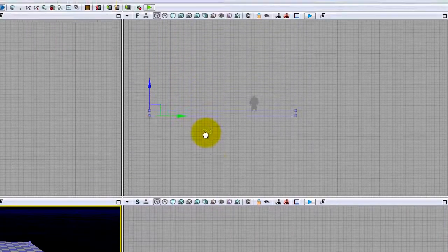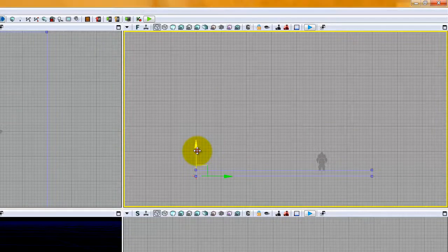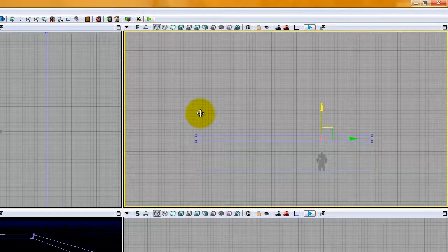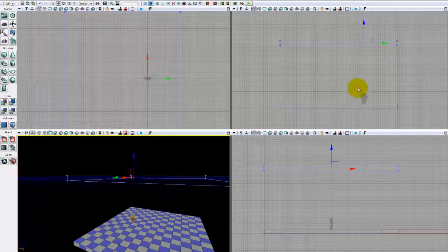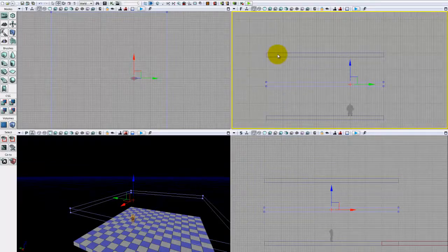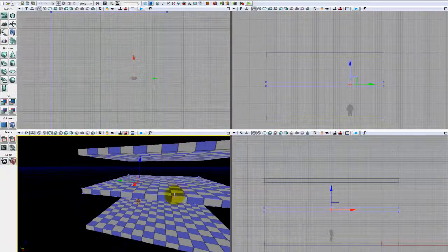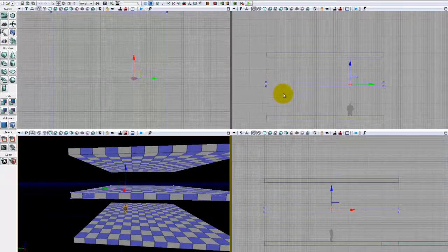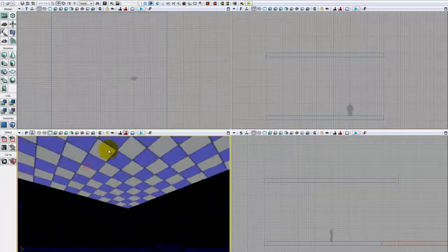And so now in camera mode here, I'm going to hold down Alt and drag this up. What holding down Alt does is it's UDK's version of a duplicate. Anytime you Alt drag something, it's going to make a copy. So if I do it again, we just made another copy. Now if I rebuild geometry, you'll see that I have 3 of these planes. This middle one here, I'm going to go ahead and delete it and rebuild again. And so now we start to construct kind of like a roof here.